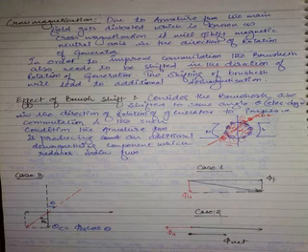Now listen, one important point here is you have two types of demagnetization. One demagnetization you have written here, that is due to the magnetic saturation of the pole half. This is one form of demagnetization, which is a small value. It may have a value but is generally negligible. But you have one more demagnetization which comes from the brush shift.